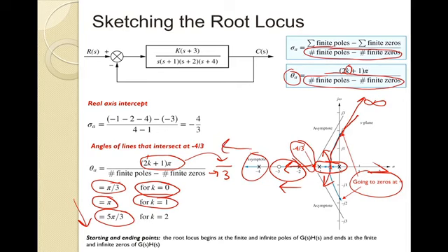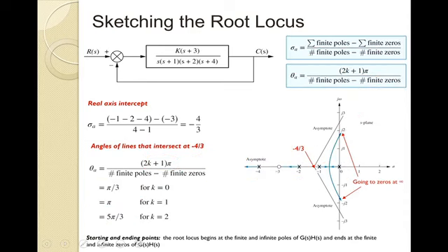And so really the dynamics of this system will be governed by wherever these two poles go. Let's erase some ink here. Okay. So this one essentially will come out of play, these two essentially will cancel, and basically these two poles will dominate the system. For example, if we want a certain damping, this is our damping ratio, we would select a value of k right about there, and that would dictate our response. So even though we had 4 poles, in the limit we can approximate this as a second order transfer characteristic because of what I had mentioned before.